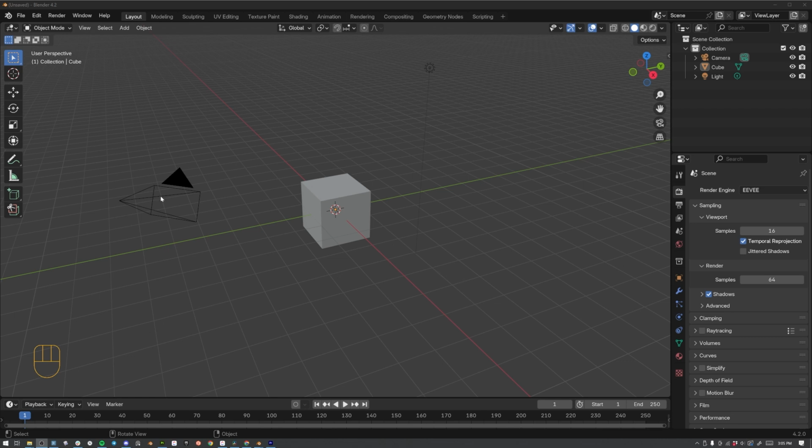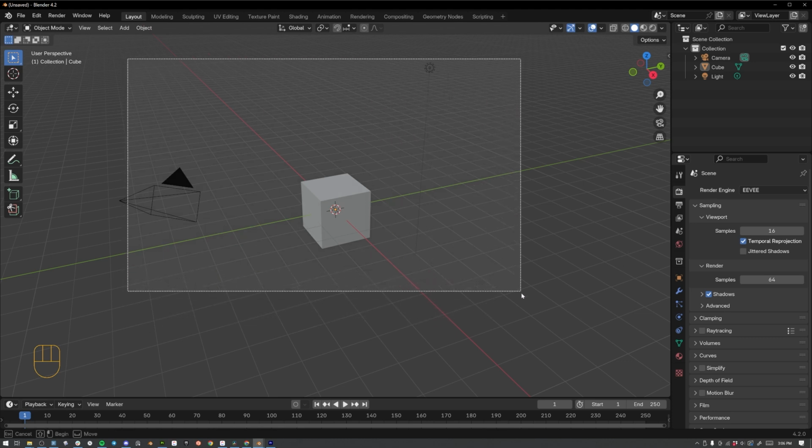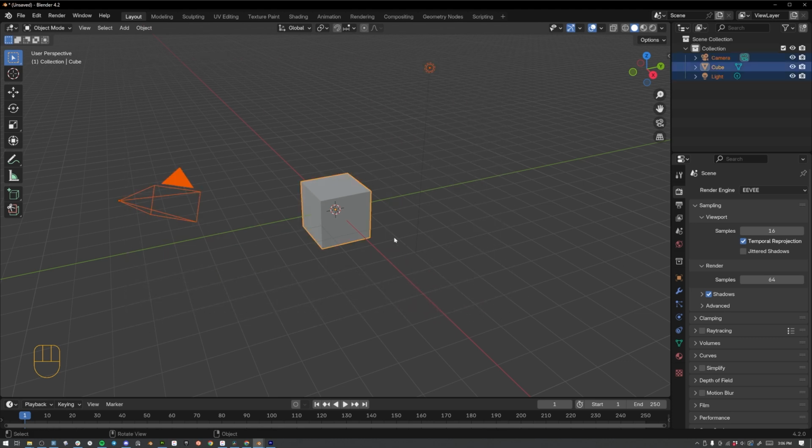This is called the 3D viewport. This up here is called the outliner, and this right here is the properties panel. So this will give you access to any details of objects that are in your scene here in the 3D viewport. Now, in order to begin, we need to delete all of these objects that are existing in our viewport now. So select all of them and hit X on your keyboard to select delete.